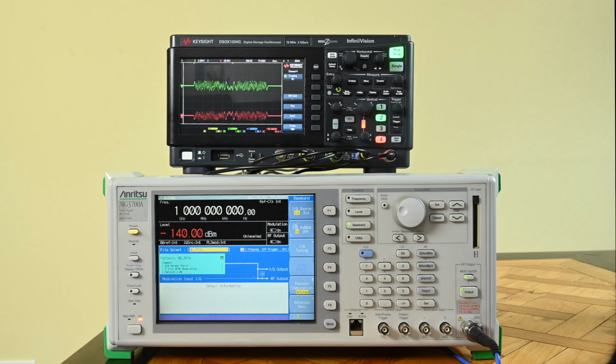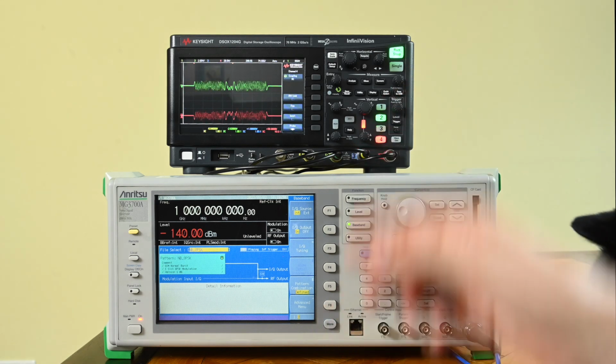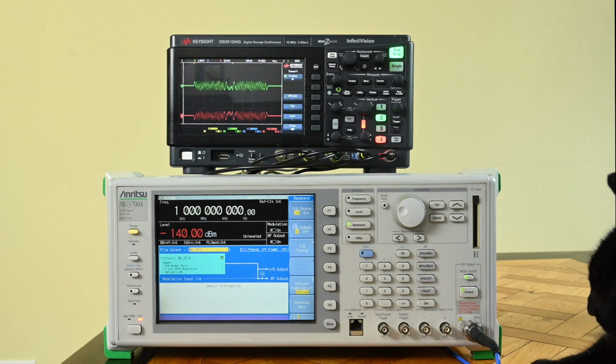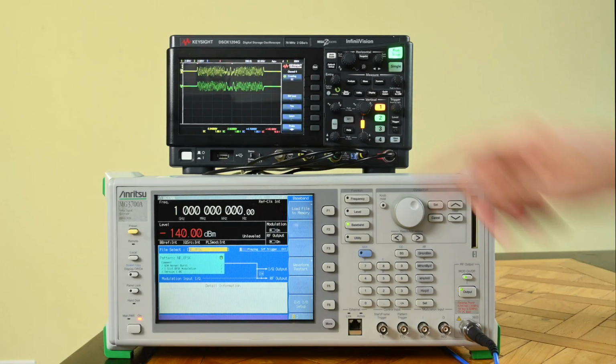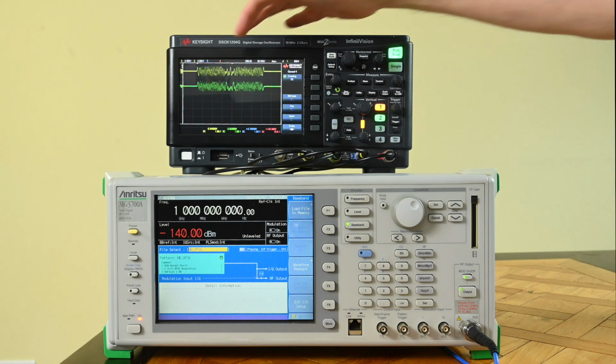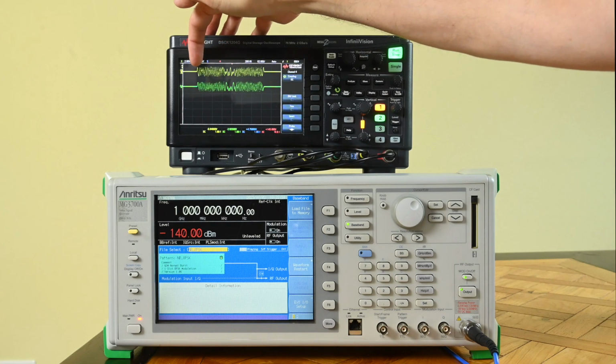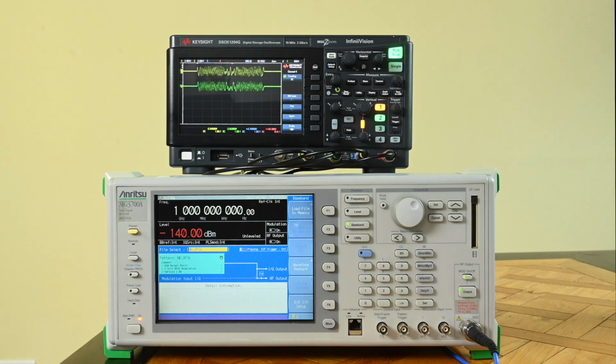So far we loaded a fairly simple waveform, we started playing it, and we look at the IQ signals here. And later I will be looking at the radio spectrum. But before doing that, I would like to look a little bit more at synchronization signals that are available in the device. Now in the waveform I'm looking at right now, I'm synchronizing my oscilloscope just by triggering on one of the IQ signals, which is fine for this burst. I'm still able to do it, but you can think of quite a lot of signals that are much more complex or actually continuous, in which you will not be able to do so.